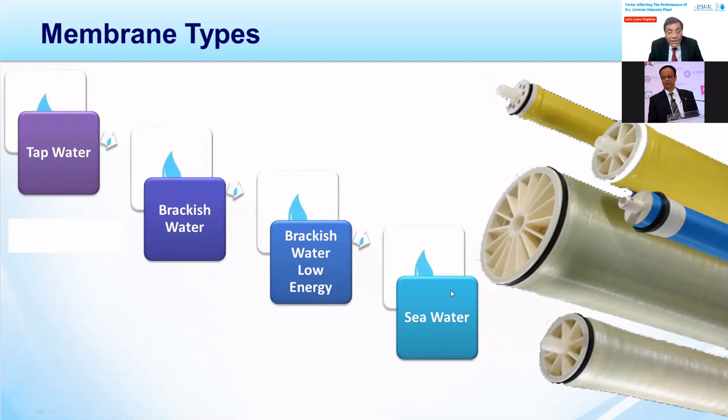Low energy membranes give lesser salt rejection as well. That depends on what type of water quality you want and which membranes are to be selected. You need to be conscious about your system. Either you want to go for the low energy membrane, the high flow membranes, or the brackish water system. That is your comparison of the operating cost as well, and the requirement of your quality.